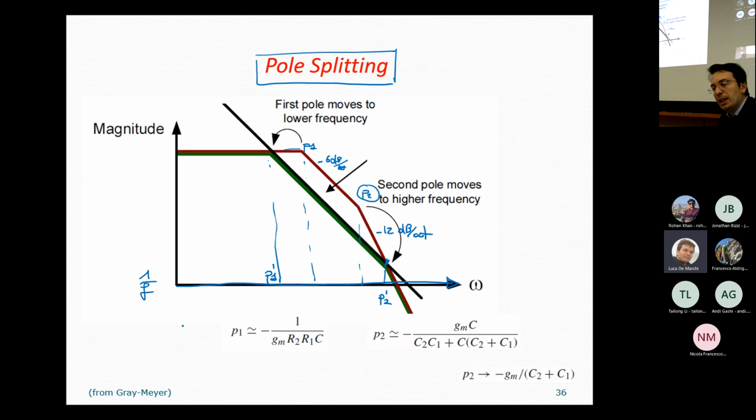Typically, I7 is larger than I5, and as a consequence of that, ICL is discharging the compensation capacitance. Okay, this means that we are discharging the loading capacitance. This is coherent with the fact that we have applied a positive step function at the negative input.